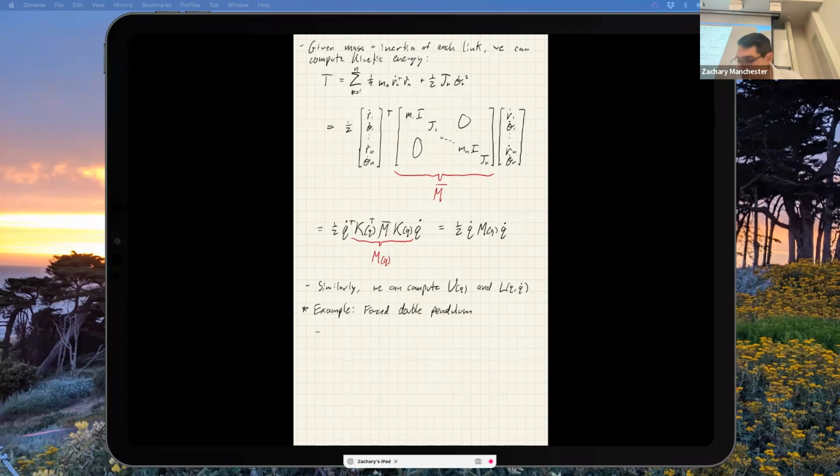Okay, so things about this. We did this in joint space, right? We wrote everything, the dynamics, in terms of joint angles. Unsurprisingly, if you do that, handling torques on the joints is easy, because those are your coordinates. I just stuck the tau in there on the end, right? And that's nice. So joint torques are easy, which is one of the reasons they're used in these serial chain manipulator things, industrial arm things.